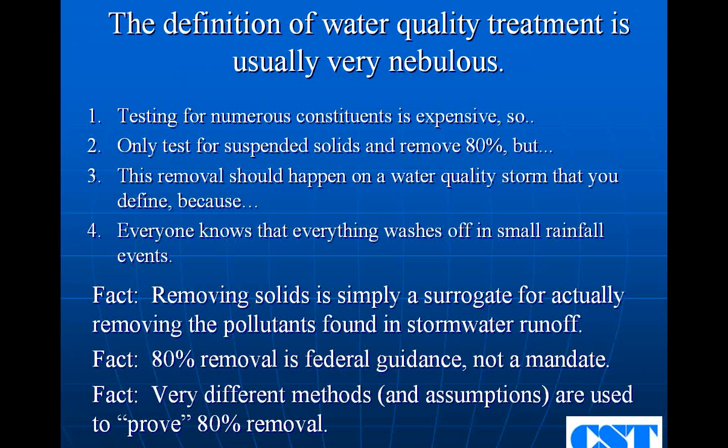The EPA said, well, you can't test for everything, and we certainly aren't going to go out and catch water samples in a bunch of storms on a bunch of different properties and analyze them in the lab. So we figure if you get 80% of suspended solids, you're pretty good. You're getting everything that we think you should get. It's a nice surrogate, and that's fine.